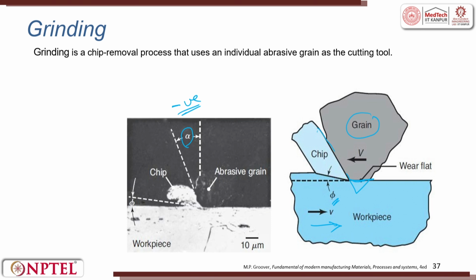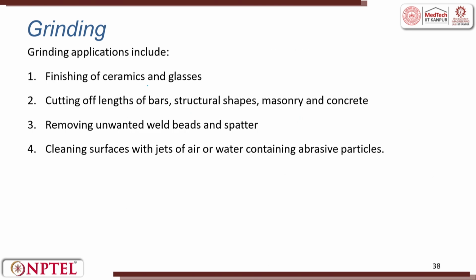Once the forces are very high, the power is very high. So, the energy used for grinding will always be very high. They are used for finishing ceramics and glass, they are used for finishing metal, structural shapes, masonries, concretes. They are also used to remove unwanted weld beads and spatter. They are used for clearing with a jet of air or water containing the abrasives.